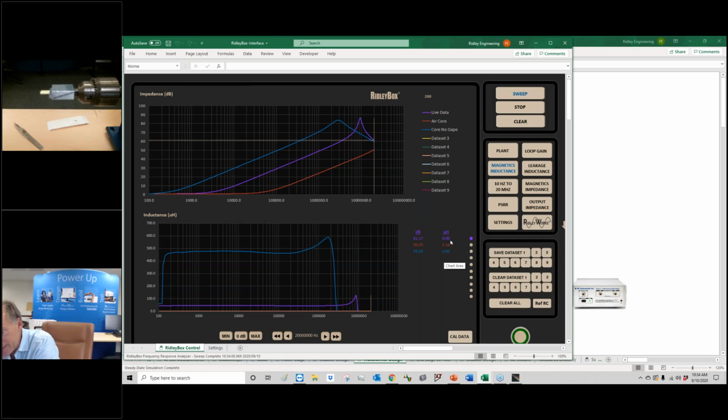When I'm doing a design here and I'm trying to quickly test out my circuit, if I'm a little bit low on inductance, I'm okay. That means I'm a little bit low on the Bmax that the core is going to see. If I was a little bit high on the inductance, I would be a little bit more careful. But that's good enough. Again, it's not rocket science, folks. It's magnetics design.